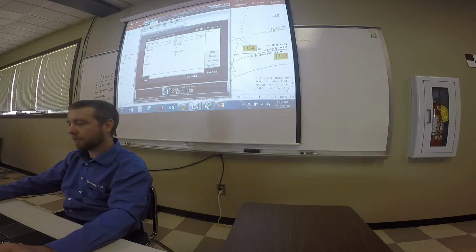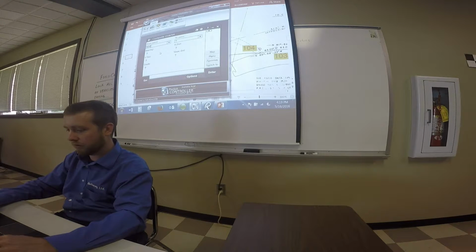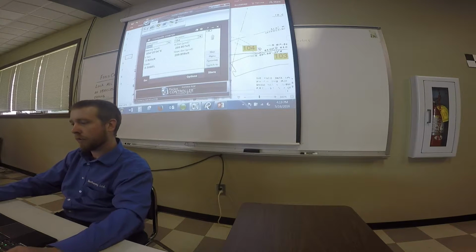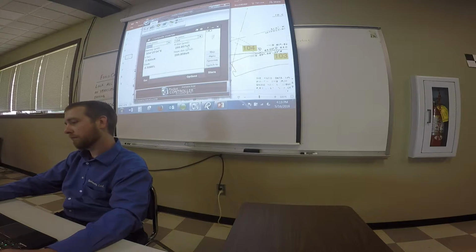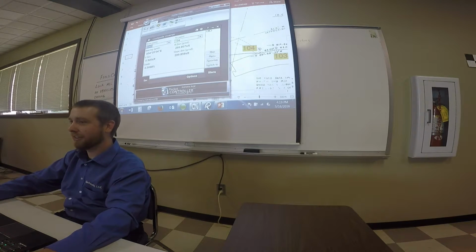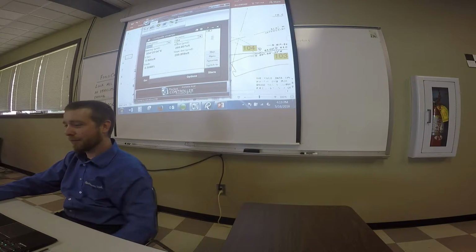Good, inverse to number 104. 299.857. So we're 16 hundredths off, which is pretty good. You can find a pin with 16 hundredths. So now you've got a stakeout point.